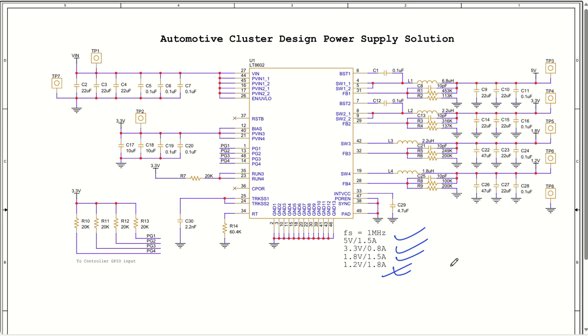As you can see, we have the input voltage here, which we are going to take up to 12 volt, or even 9 volt to 12 volt we can give. It is capable of taking up to around 30 volt also, but to have better efficiency, try to limit your input voltage to around 12 volt or 15 volt. Nicely designed input capacitors, and then the output voltage is made here.